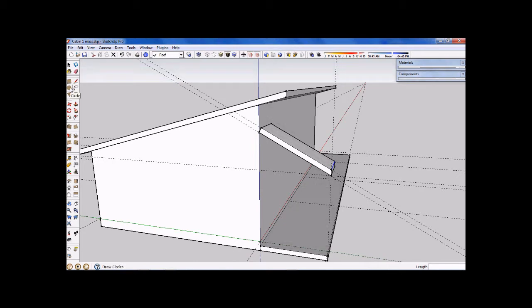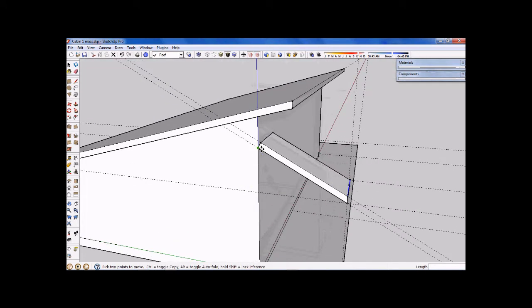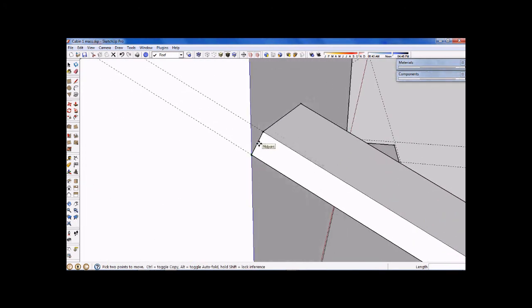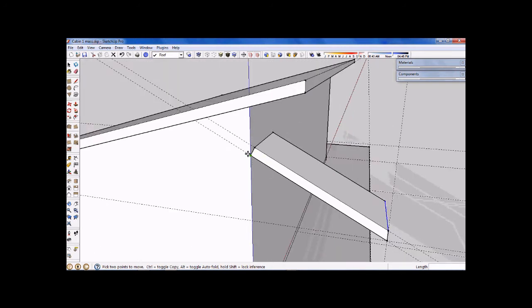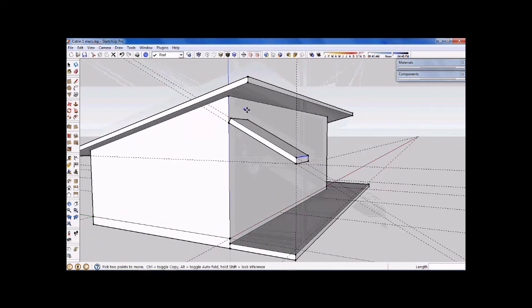we do need to do something very similar to that, but I've just got something else in the back of my mind. I'd really like to pull this edge that we've got at the moment a millimetre away from that wall surface. Why I want to do that is I'd really like to keep this wall surface intact and not intersected by anything else at the moment.